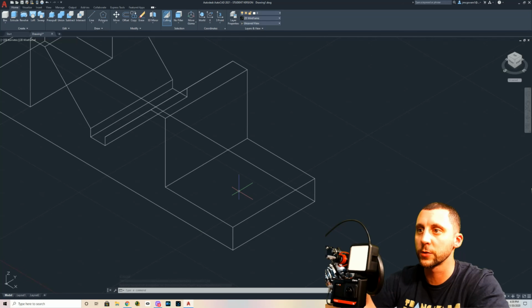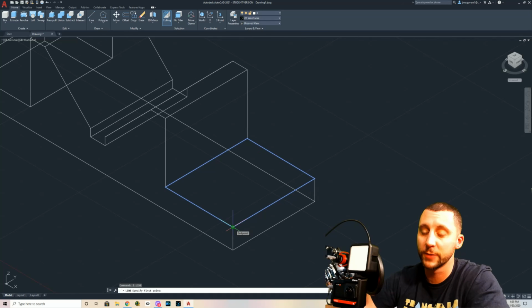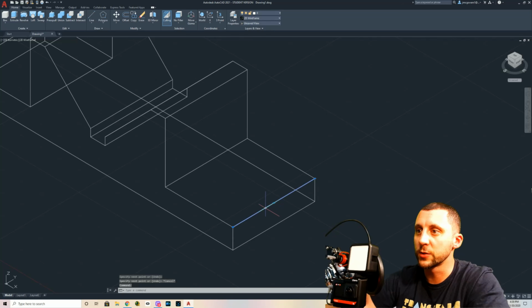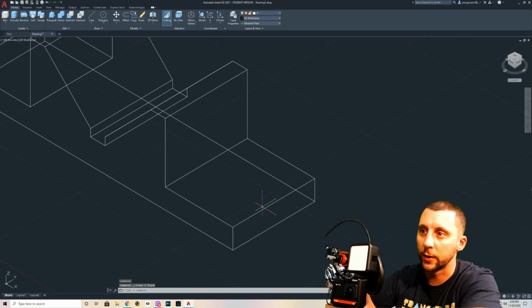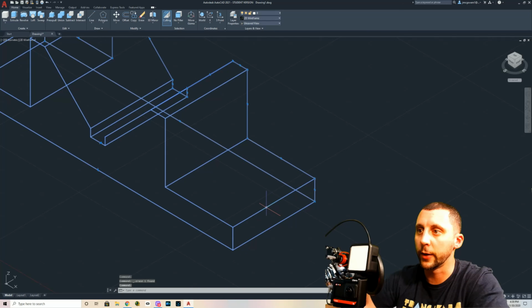We've got to extrude the circles, and then we've got to subtract them away. So if I go like this and I put this, this is definitely a dummy line. Okay, this line will get erased. The reason why I'm drawing it is because you can't offset a 3D model. Without that line, this is just a 3D model and it can't be offset. With that line, I can offset across that top surface.